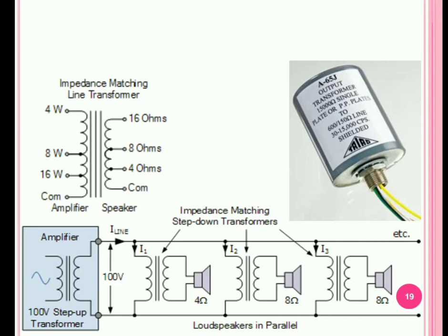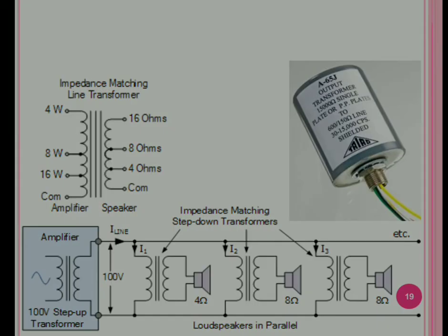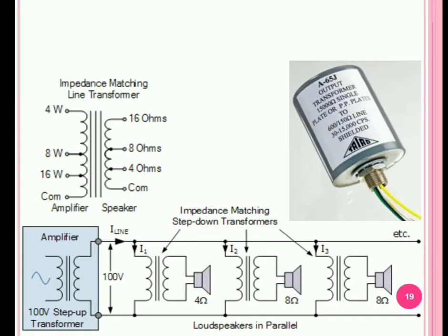On the amplifier side of an amplifier, actually this is an audio amplifier, a bigger one, and then the output secondary winding you have 4 ohms, 6 ohms, 16 ohms and 8 ohms tappings. That means the input also you can pick up. You have the choice to select what wattage you have to take into, depending on the output load, that is the loudspeaker you are going to connect. Again, you can also use different tappings of the secondary to match that of the speaker that is in your hand for the connection.